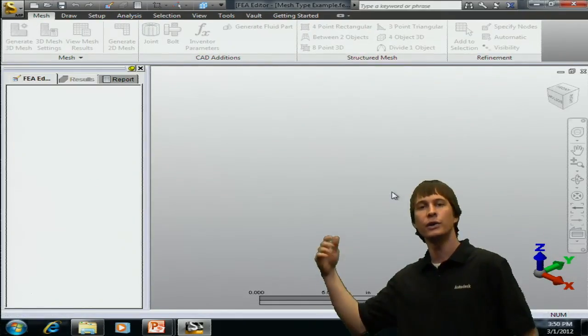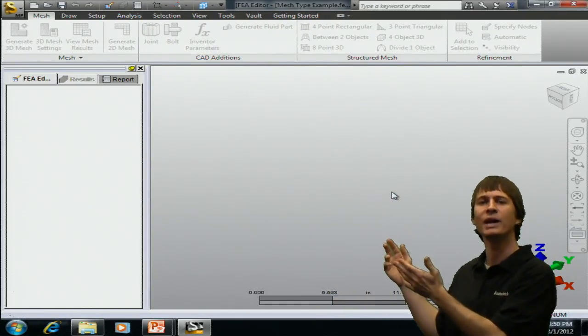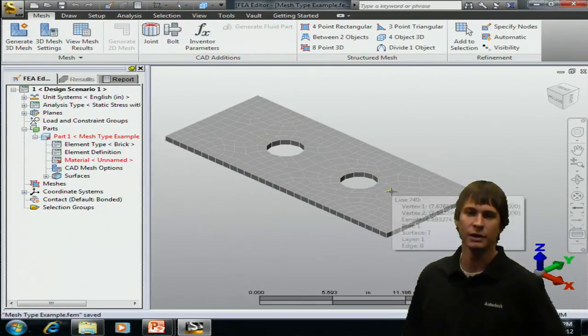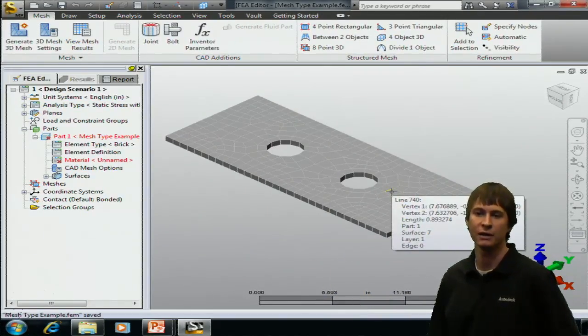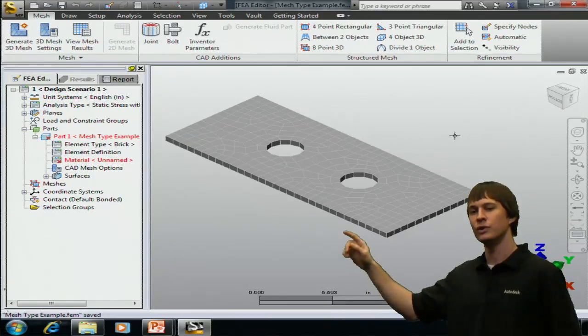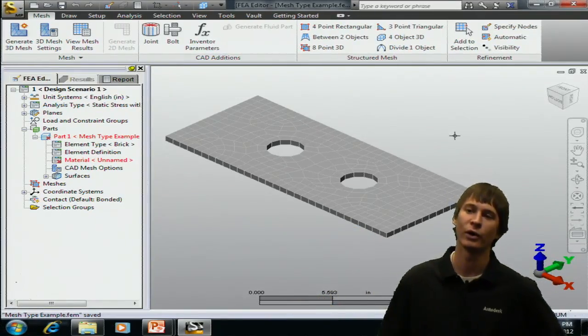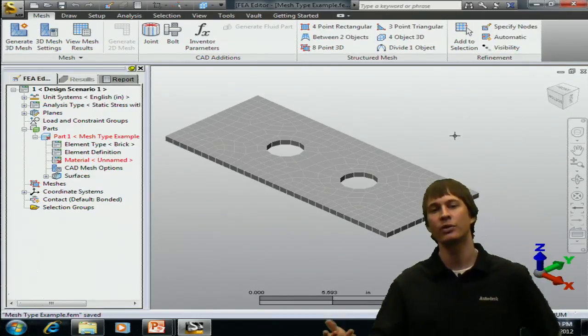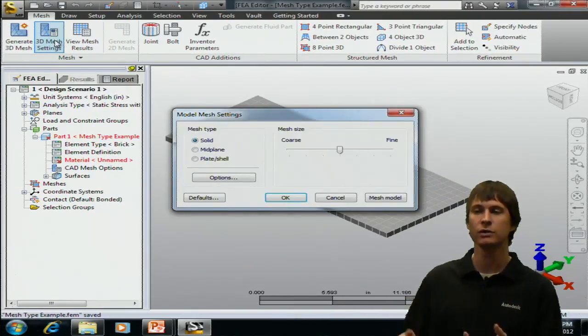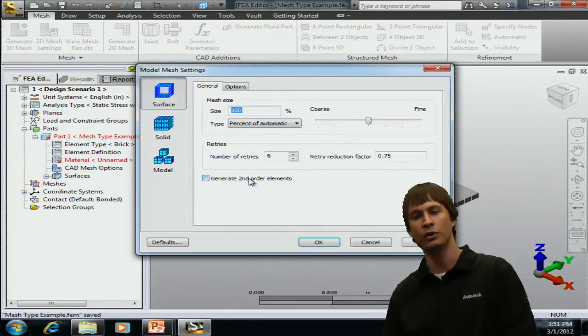When we do so, you're going to see that although we have a fairly nice surface mesh on the model, it really isn't acceptable for our analysis. You can see that there's only one element through the thickness. We want more elements in there. So let's try it with the tet mesh. Tets are usually smaller, so maybe we'll fit more into that small thickness of the part.